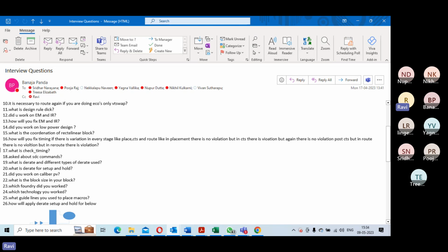And multi-voltage is not just like this. You also have DVFS, dynamic voltage and frequency scaling, where you can have an on-chip voltage regulator which can dynamically change the voltage. How you manage that is a different topic, but these two techniques at least you can remember. In a shut off, you'll have power gating cells, isolation cells, and you can have retention if that is a requirement. Of course, always-on cells and breaker cells will be there. These things are all required.